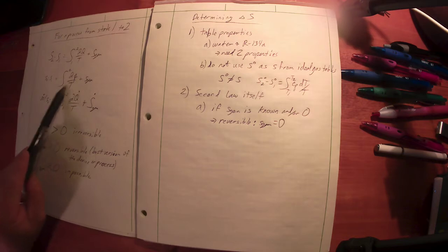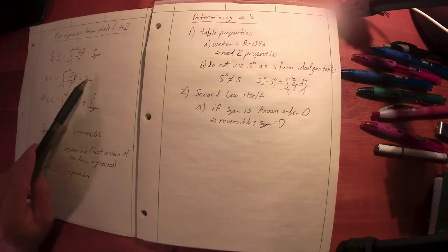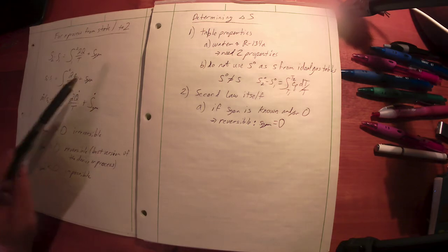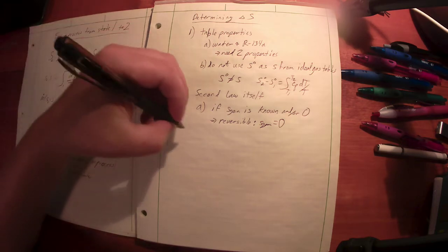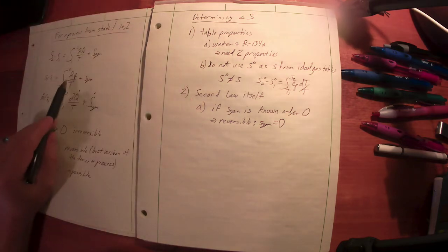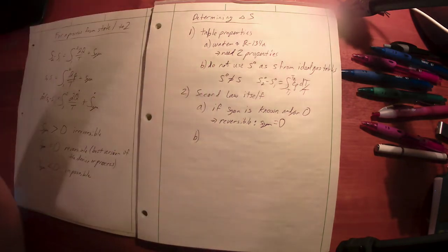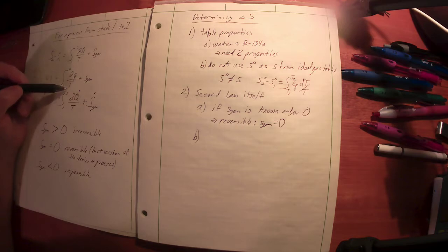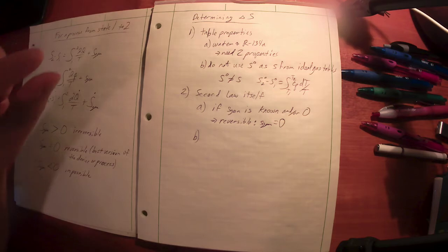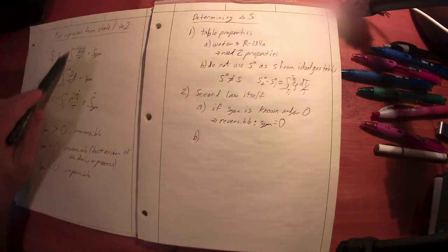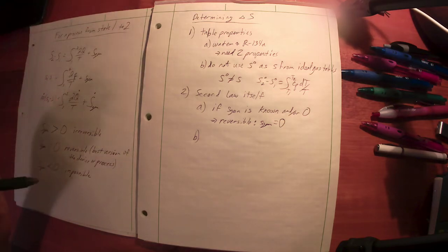That means I need to be able to quantify these two terms. There's two things that can happen with this. Either this is what we're solving for, or it's a known quantity, and most likely if it's known, it's 0. Okay? The other thing is what do we do with this crazy partial integral? Well, it's really just the sum of Q over temperature that this represents. We're just saying you can break it down into every little differential slice of heat. That's why we write it as an integral, but it's really just the sum of Q over T, where Q out would be negative.